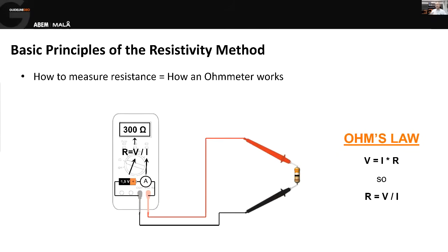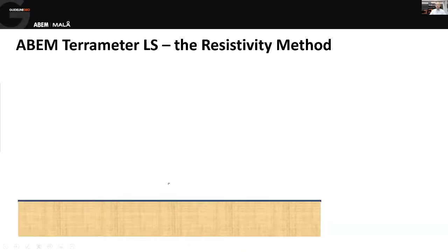Now, in a laboratory, doing those measurements is really easy. We can just use a simple electrical test meter with two probes. We put the probes on either side of the component that we're interested in, and Ohm's law will give us our resistance by knowing the voltage in the battery and the current flowing through the circuit. For the real world, it's a little bit trickier.